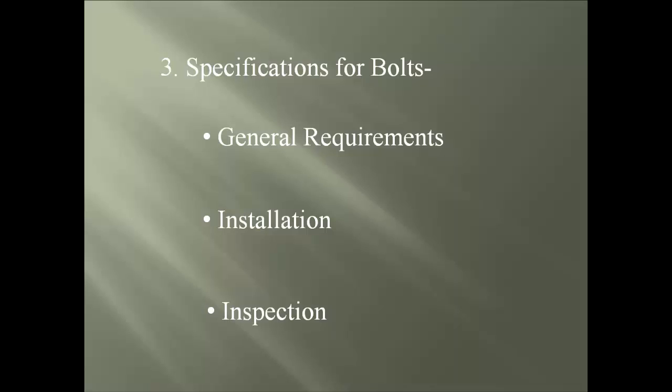And the last item of this segment is the inspection, which when required by contract documents ensures the work in progress meets this specification. The following joints are covered: snug tighten, which must be visually ensured that all plies in the assembly have been brought into firm contact.